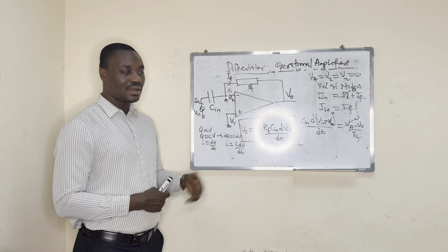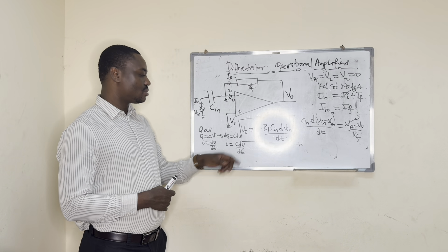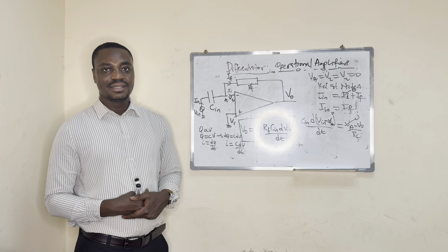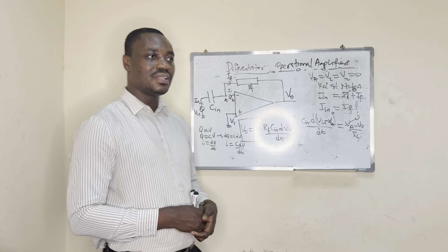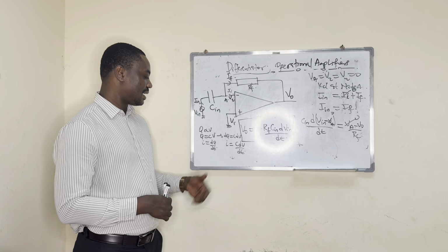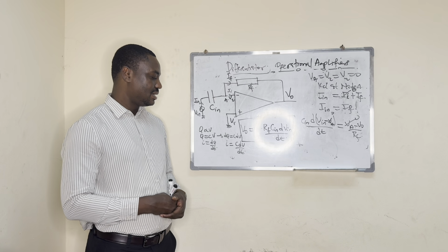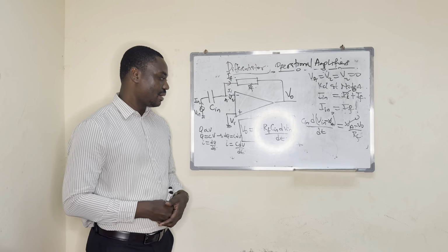If you take a small amount of the accumulated charge, that gives a small amount of voltage, so dQ equals C times dV. Current equals Q over t, the rate of flow of charges. Replacing, we get I equals C times dV over dt. This is the general formula for the current passing through a capacitor.